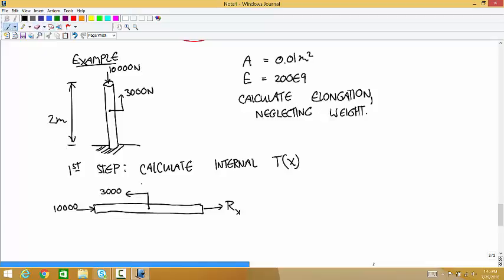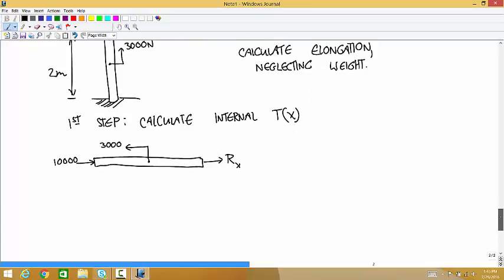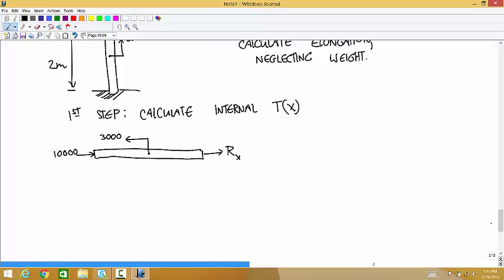And if we're just trying to calculate the internal loads, we can skip what's happening at the right endpoint. If I had flipped it the other way and worked from the ground, then we would have had to calculate that. So what's n? How many points do we have where the subfunctions could change? 3. Yeah, n is equal to 3, so we're going to have to do 2 cuts. Cut 1 is from the left end to the midpoint, so that's 0 to 1.